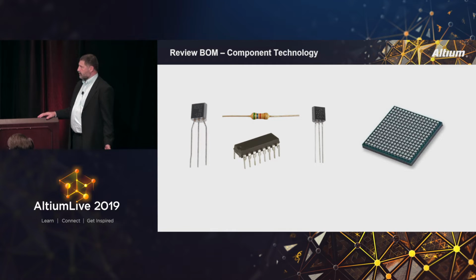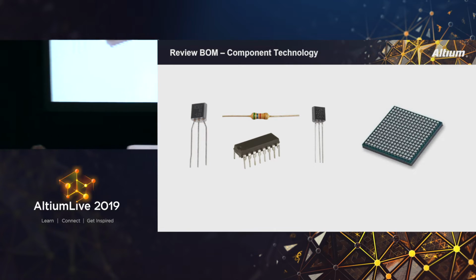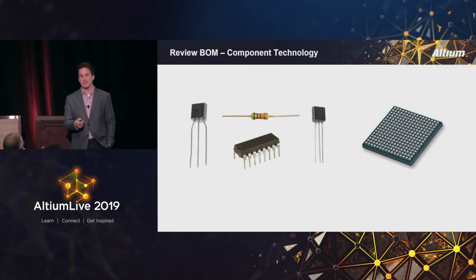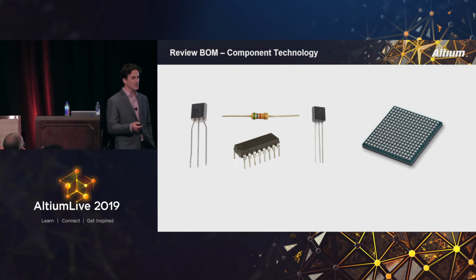The outer 2 rows we can get, but then we have to get the next 2 rows, and the next 2, and the next 2, and we just keep adding layers. And I'd say especially if that BGA is 0.5 millimeters, you have to have a serious discussion about the cost associated with adding that part.